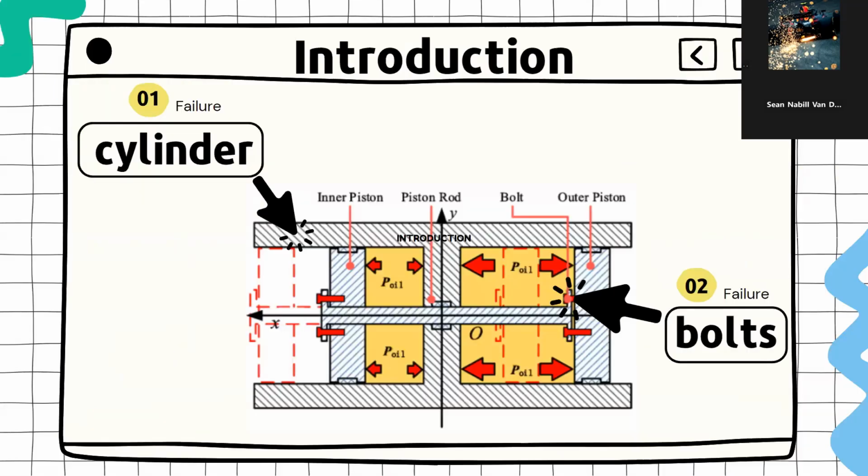This section focuses on the failures in the key part of the underwater glider called the buoyancy regulator, which helps the glider with adjusting its buoyancy. The study concerns two main problems. The first dilemma is the overall shape of the buoyancy cylinder, as its ovality can affect the sealing ability and surface scratching. The second dilemma centers on the bolt failures and issues of overloading the piston rod bolted onto the outer piston, which applies too much pressure on the bolt itself.